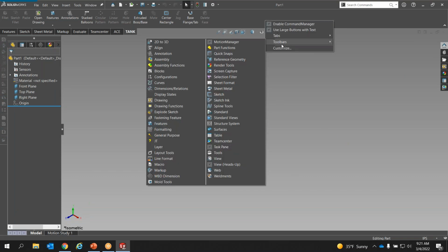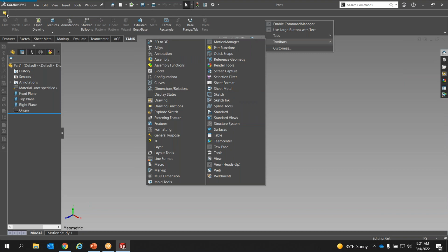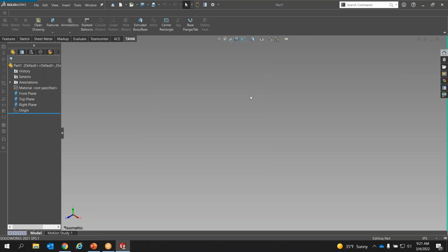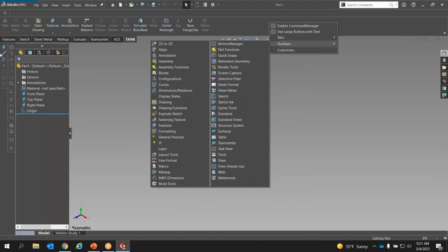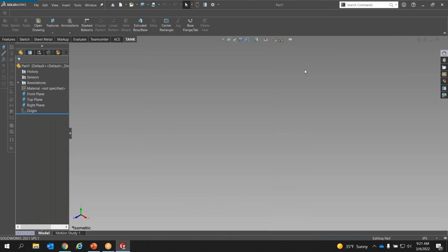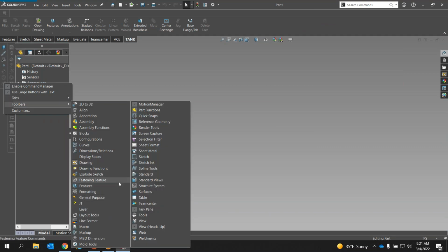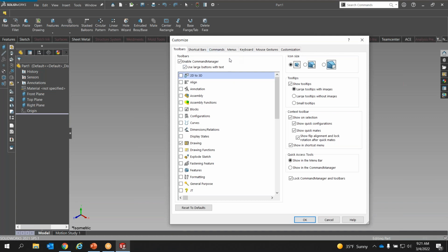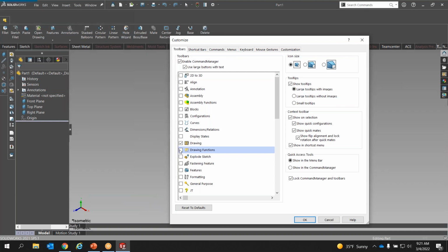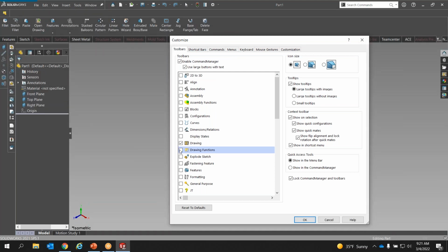I'm going to do a lot of part functions. So we're going to throw some part functions up there that allows us to pick some things. And let's throw some reference geometry in so we can throw our planes and whatnot in. And with those, you can come over here, find your toolbars, hide and show them, if you want to throw them in, click and hide them there.